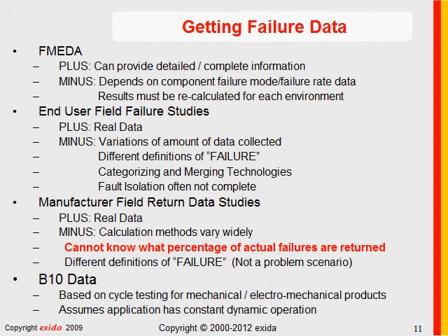How do you get this failure rate data? I will readily admit there was a time back in 1996 when the first ISA SP84 standard was released, introducing the performance-based functional safety concept. The whole idea of doing calculations was kind of tough back then because failure rate data was a bit hard to come by.